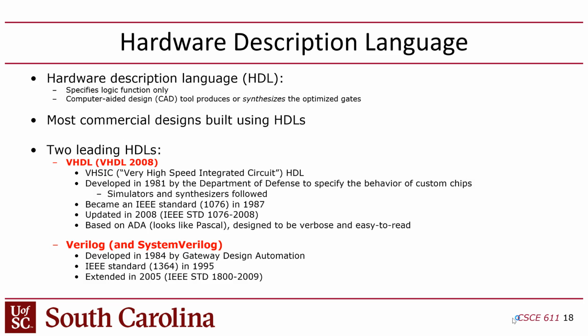So VHDL was originally written as a specification language. It was to basically say, this is the behavior of the chip in a way that is reproducible and precise, and it's down to the clock cycle. That way, if I contract you to build this chip to control that turret on the tank, it has to match exactly what the behavior is defined as in this language, right?